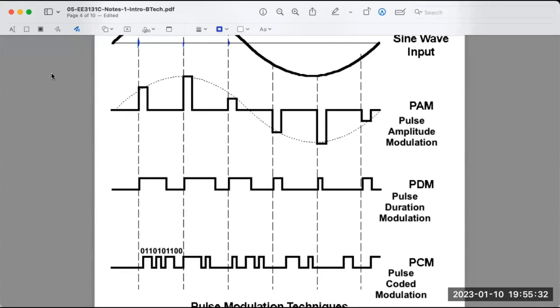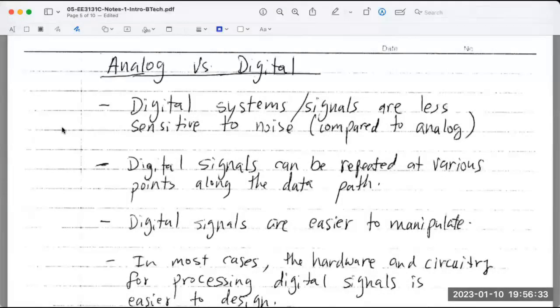Now keep in mind that in this class, we're going to talk about modulation, but this is not that modulation. This modulation is to generate a waveform that you can transmit. Typically, we don't transmit these kinds of waveforms. We're going to take this waveform and move it to a carrier frequency. That is typically what we mean when we talk about modulation in communication systems. This is what's called baseband signaling. This is at 0 frequency, meaning the center frequency of my modulator is 0. But this is still called modulation because it takes bits, ones and zeros, and generates a waveform that you could transmit.